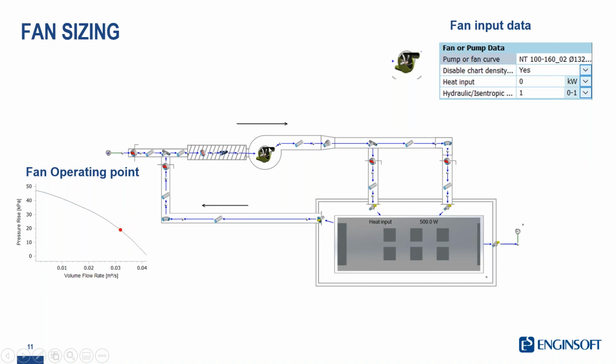So you are able to select the correct vendor, to select the right fan that is not too much for energy consumption, and you are able to calculate the global pressure drop and the operating point when you select one of the vendors that you think is the right one.